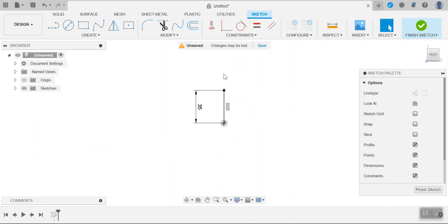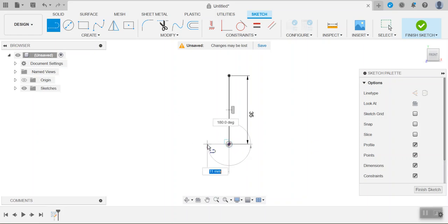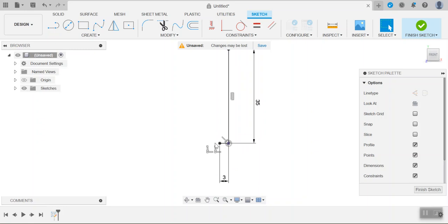I want 35. Then I'll move this across, so I like to draw on the left hand side. I'll type in L again, left click drag. I only want half the diameter for the radius, so it's going to be 6.5. And let Fusion do it for you, so divide by 2. Enter. That gives me now my radius. Hit line, left click, drag up for our height, the depth of our hole, which is 15. You can make that different to what you want and hit enter.